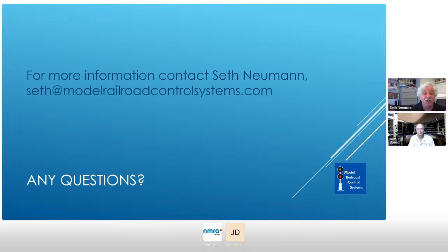The good news is you are much more likely, with a new computer, to have them already, and the process for doing it is fairly simple, and we've documented it in several places. So what you're usually down to is a USB cable, the Arduino IDE, and installing the CH340 driver if you even need it. And I won't completely minimize it. It is an issue that sometimes crops up.